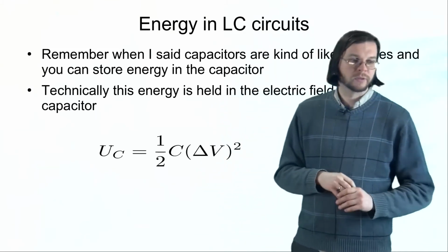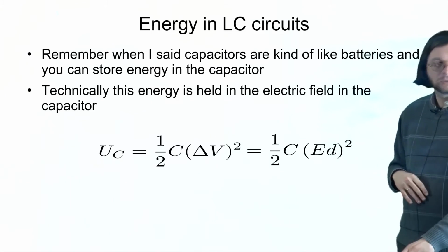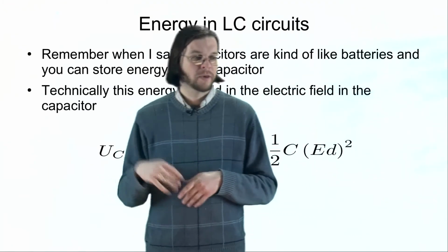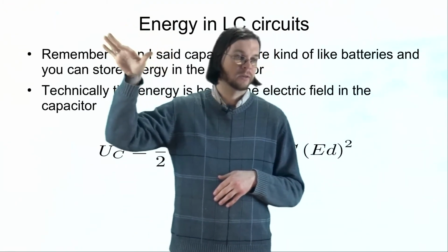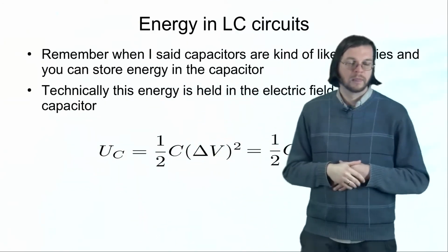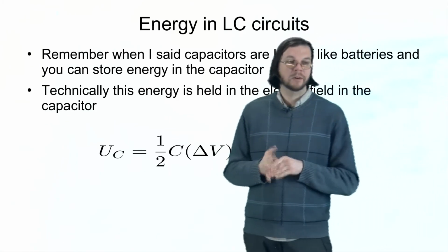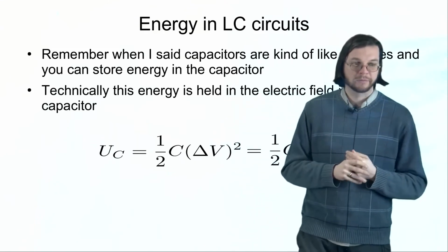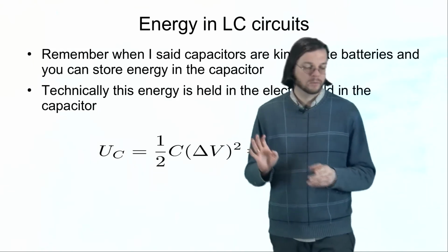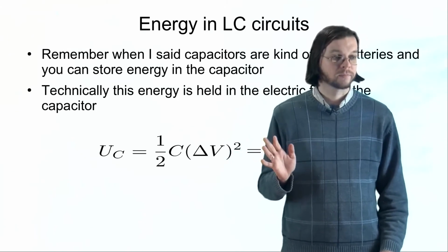So this is the formula for the energy held in the capacitor, which is that. I think it's also Q over C. So there's energy stored in the capacitor, but there's moments where the capacitor in that situation, the LC circuit, has zero charge on it, zero voltage, but yet the circuit keeps on oscillating. And so what's happening in those moments is that the energy had to go somewhere. We haven't lost any energy because we don't have any resistors attached to the circuit. So where did that energy go? And I've already said it once or twice that the energy needs to go into the solenoid, into the inductor.